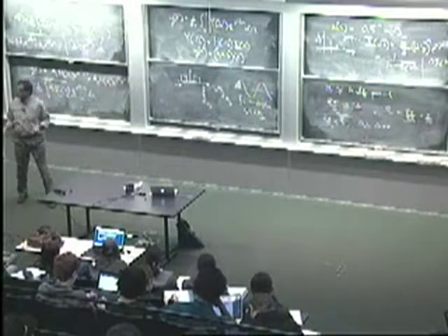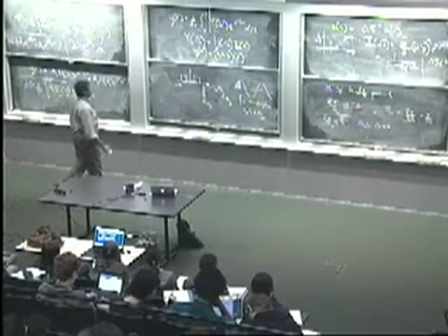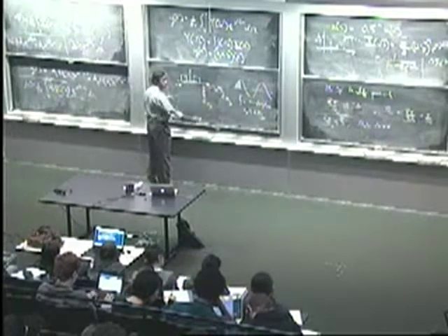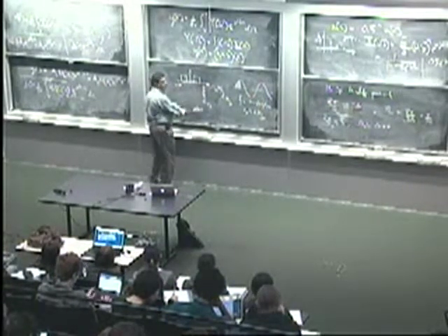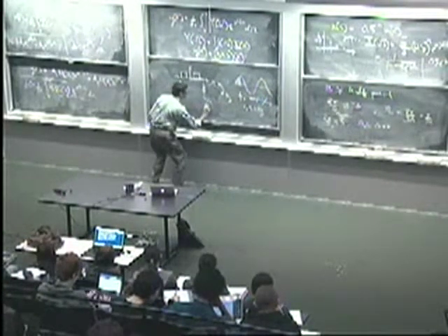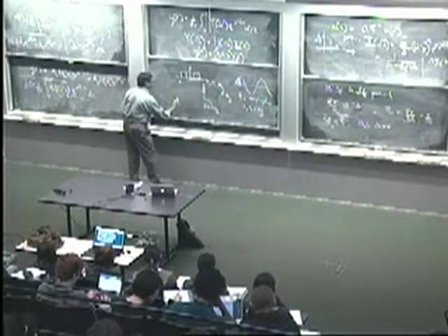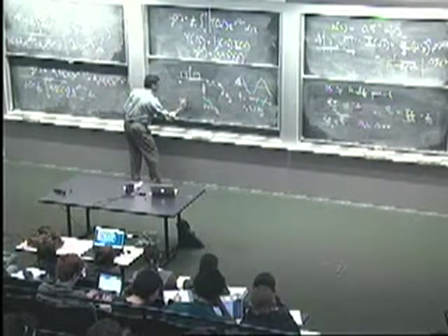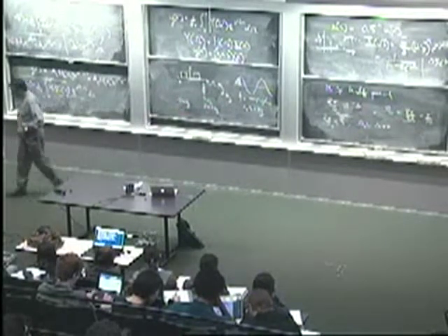You get a discrete time sequence out of that. You do various DTFT type computations, spectral content or frequency response, and you plot them on this kind of a scale. If you want to think about what the underlying continuous time frequency is, well, it's 24 kilohertz in this case. And minus 24 kilohertz sits at this end. Okay?